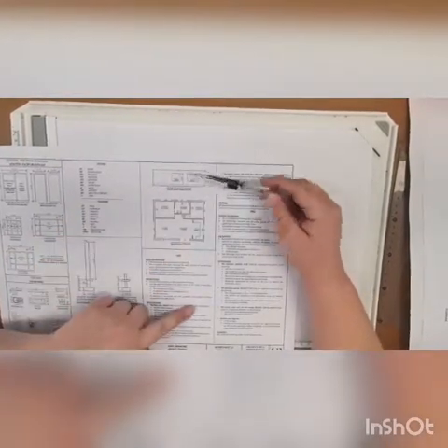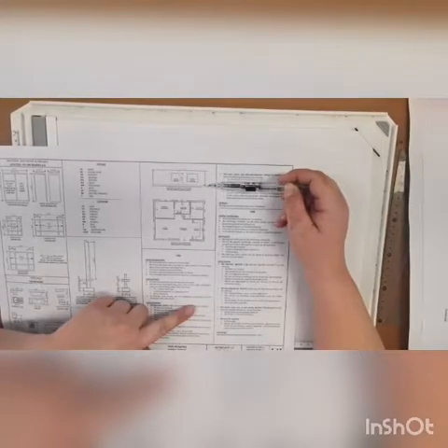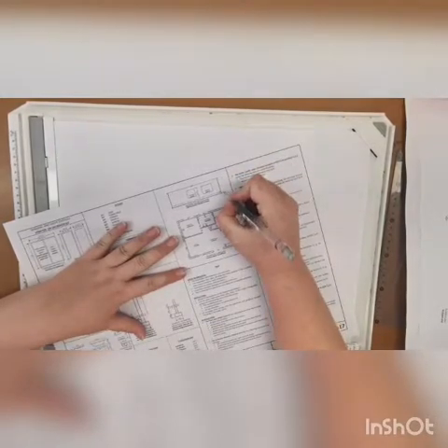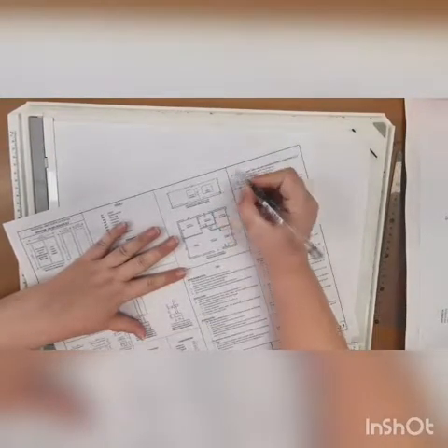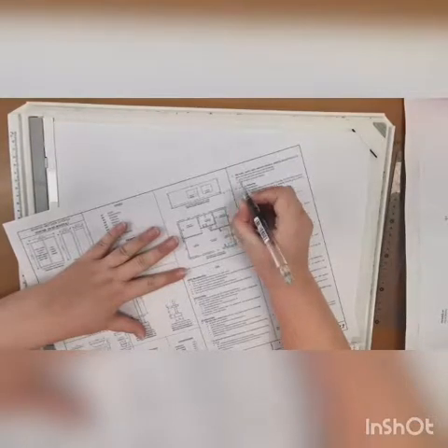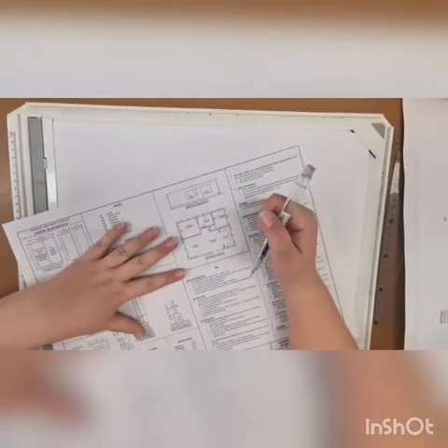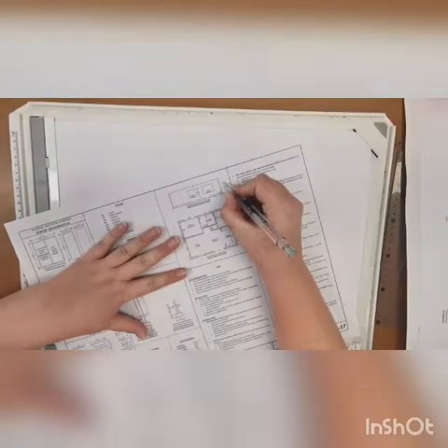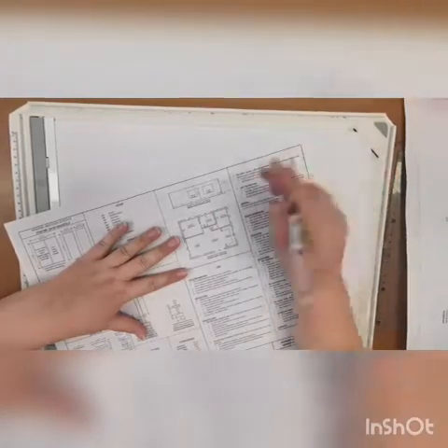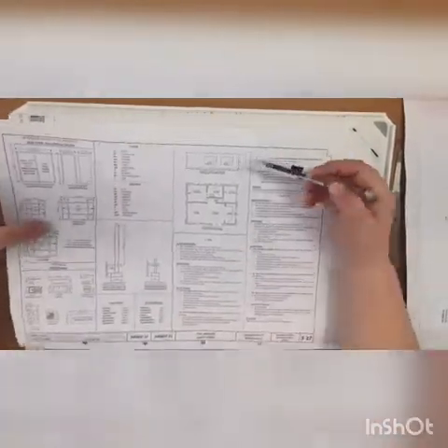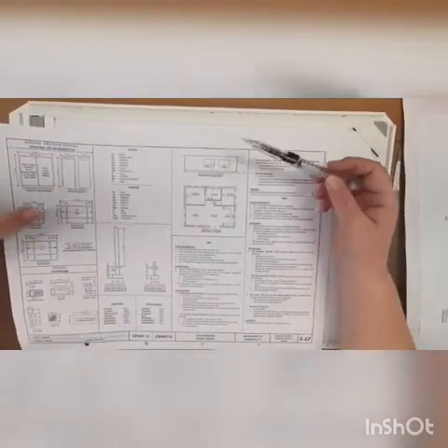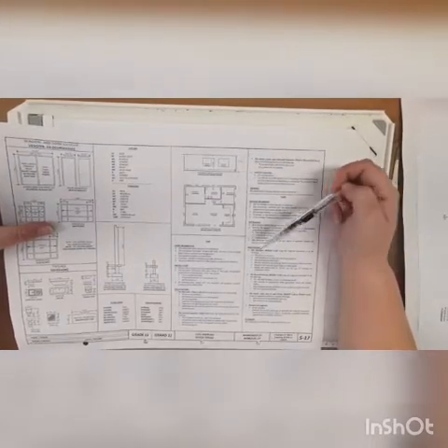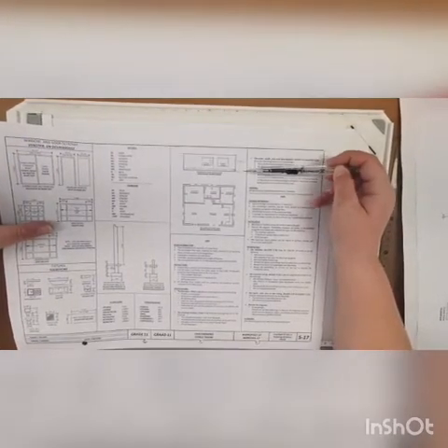Okay? Here they have not given you the height of the wall or the height from the ground line to the finished floor level. In real life, the height from the natural ground line to the finished floor level is 170 millimeters. Then the height to the top of the wall is 2761 millimeters, unless they have given it. So please make sure if you're writing an exam or something, you look. If they have given you what they want, use that. If they have not given you what they want, you need to remember those.